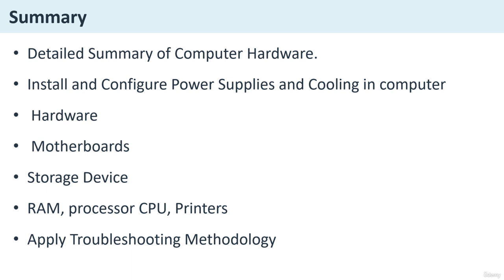Now, the power supply efficiency and voltage rails. Power supplies convert AC, that is the alternating current, from the wall into the DC, direct current, for computer components. They have different voltage rails. Number 1 is 3.3 volt, which is used for older components and some motherboard functions. 5 volt is used to power USB ports, some storage devices, and older hardware. And now 12 volts, the most important rail, used for CPU, GPU, and high power components.